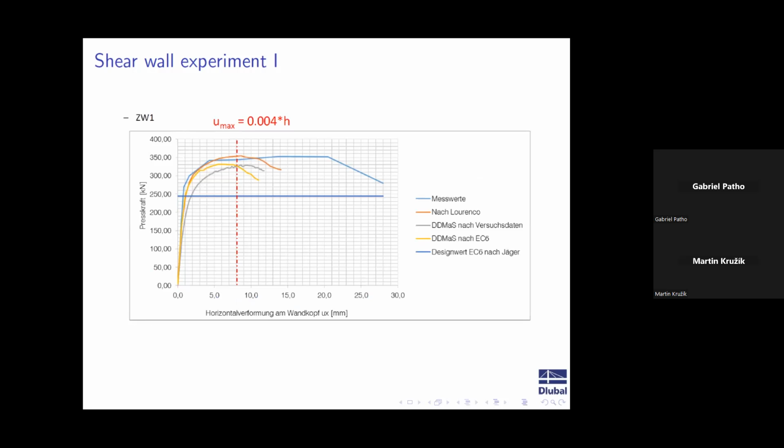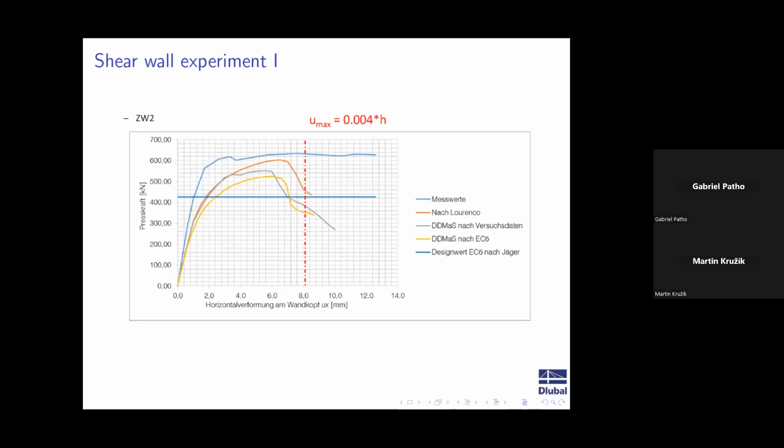What this blue line is, what you would do as a civil engineer as a hand calculation. So this is where you would put your yielding. This is where you would stop and say that you need to refine your structure because it's overloaded. And some different test scenarios again. We are on the safe side. This is basically what these tests are telling. If we are close or not to the actual data, hard to say. So far, this is the best we can do.